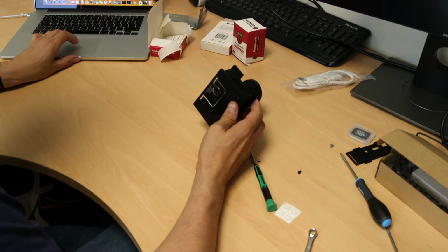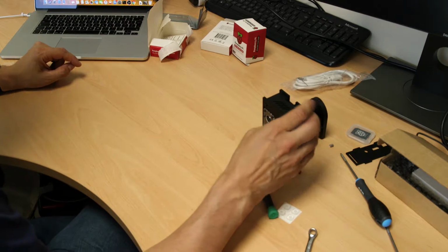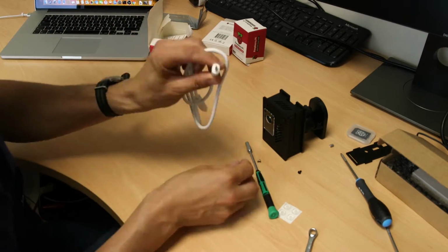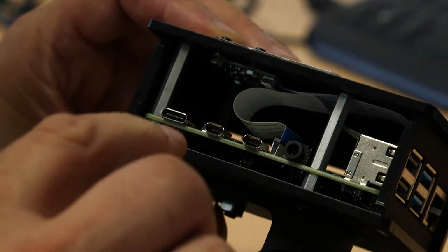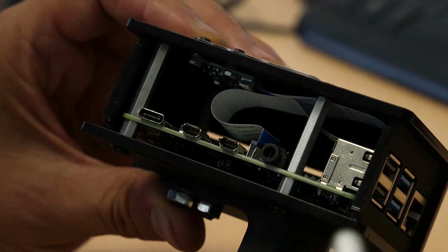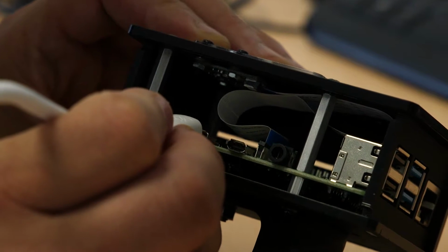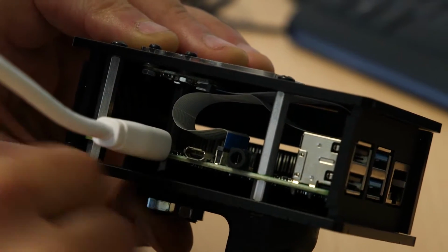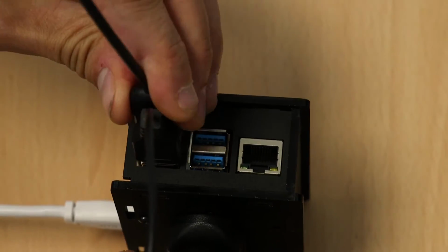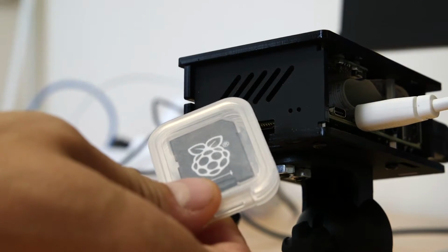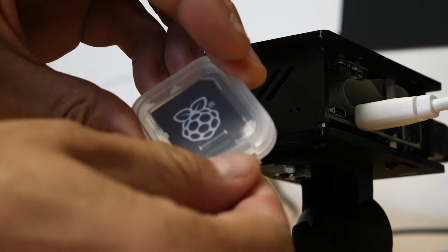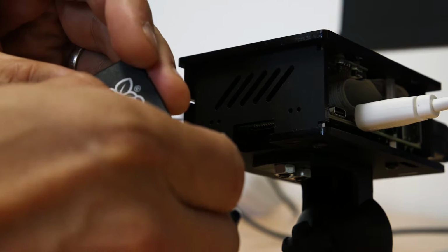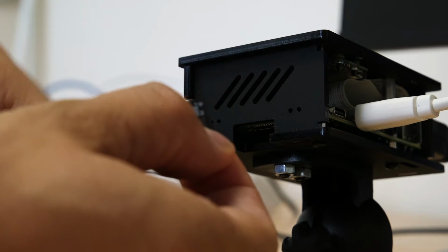Okay, so I've built the thing. Now plug in monitor, mouse, keyboard. On the Raspberry Pi 4 there are two mini HDMI sockets, and you should plug the HDMI cable into the one labelled HDMI 0. Before we connect the power, we're going to need to insert the SD card, which you'll find inside here. So there's an adapter and the SD card is there.